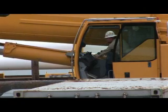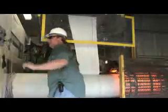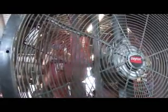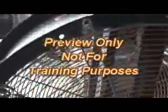Use equipment that has air-conditioned cabs when possible. Reduce workloads through scheduling. And always encourage the use of power tools and machinery to reduce physical exertion. When working inside, have air-conditioned areas for breaks. If possible, air-condition the entire work area. Utilize fans and ventilation systems to increase airflow in the overall area. Portable cooling fans can provide relief to certain areas or individuals.